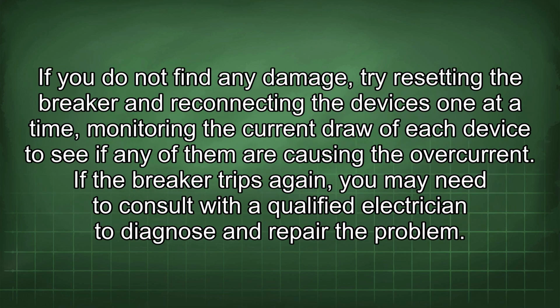If you do not find any damage, try resetting the breaker and reconnecting the devices one at a time, monitoring the current draw of each device to see if any of them are causing the overcurrent. If the breaker trips again, you may need to consult with a qualified electrician to diagnose and repair the problem.